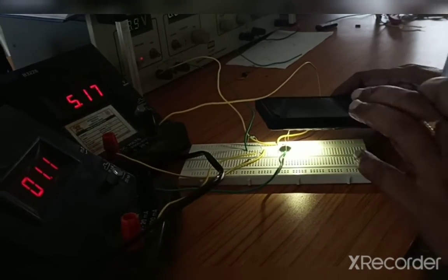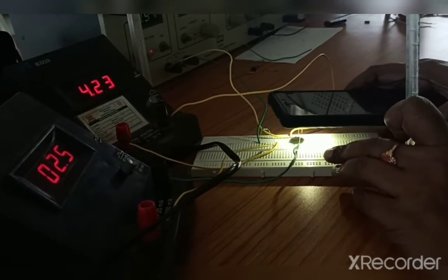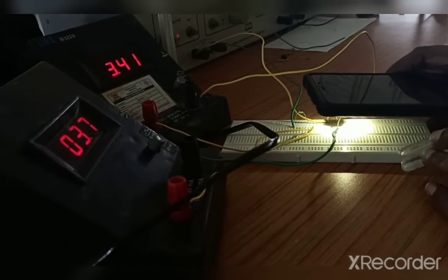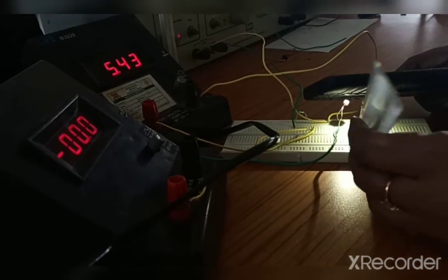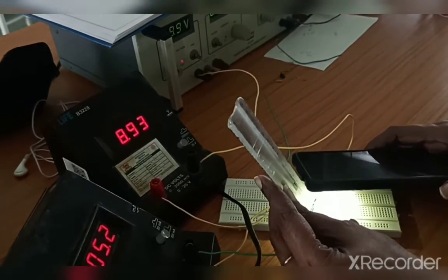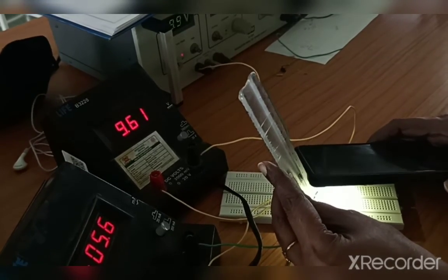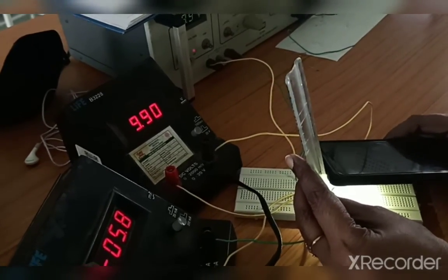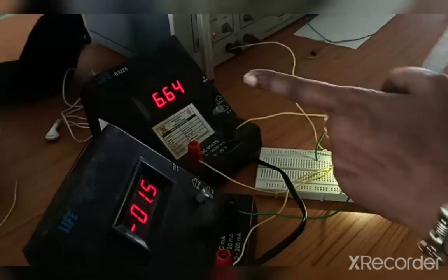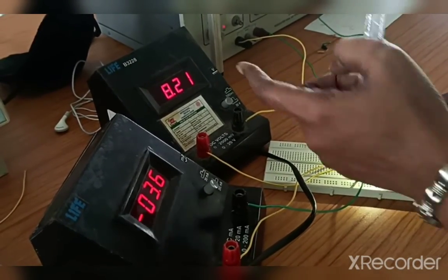For the same circuit, give the square wave input also and compare with the various waveforms. Make V reference equal to 0 and observe that the corresponding peak is clamped to plus or minus 0.7. The result is that the clamped waveform at the desired level is obtained and the clamping circuit is studied.